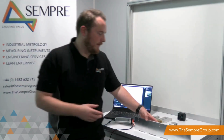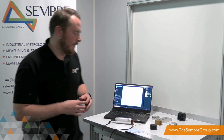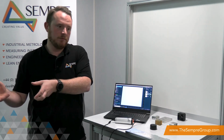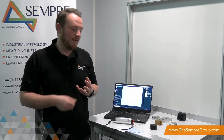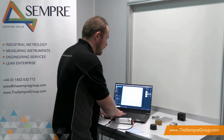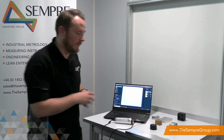we're starting to see a lot of our customers that manufacture larger samples, so this is an example of one, that they're struggling with having to take the sample to an inspection machine to be able to measure things like radiuses, break edges, chamfers, fillet reliefs, that kind of thing. So the idea behind using the GelSight system is we can bring the system to the part as opposed to the part to a measurement system.